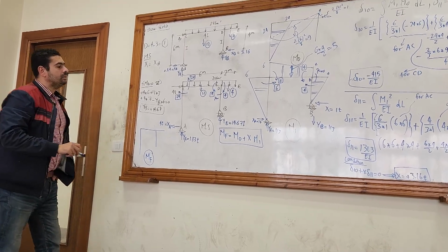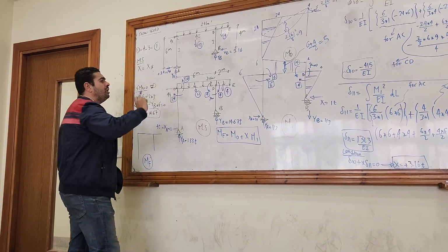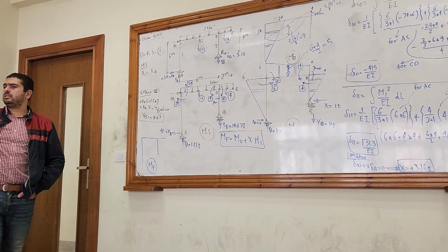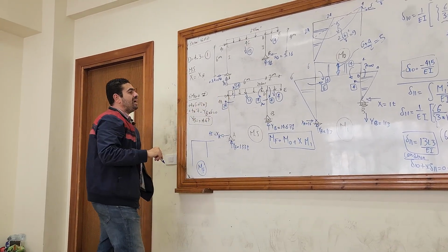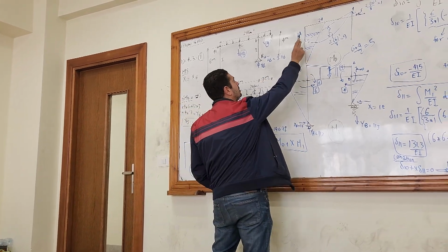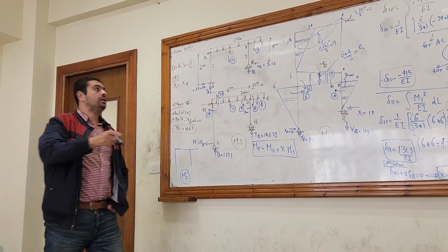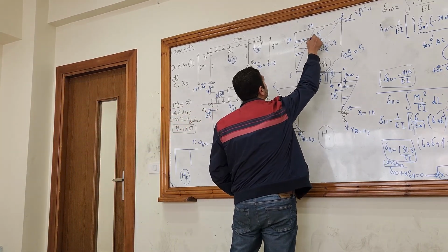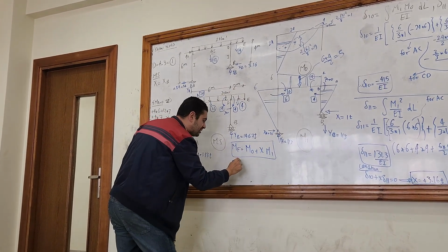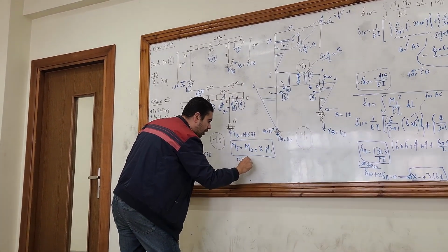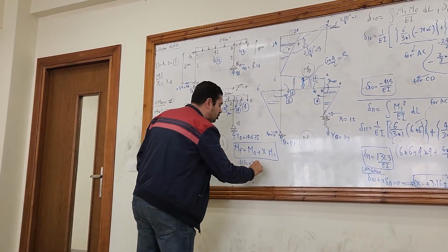And then calculate this equation only at the joints. Only at the joints, okay? At joint C, what was the value of M node at joint C? Including the signs. Here, it is a positive moment, right? So at C, it was positive 24, plus X. What was the sign of X?